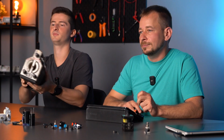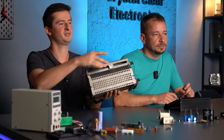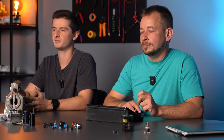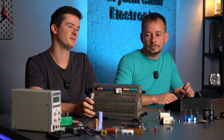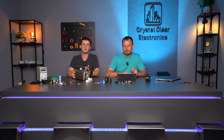It is a power resistance I bring up as an exotic example. You can guess from the multiple outlets and the slider that it is a high power potentiometer. I use it most often to warm up tests on power supplies for my new circuits. The maximum value I can set it to is 5 ohms, so for example I can test a 5 volt supply initially at 1 amp, then by moving the slider I can reduce the resistance, increase the load. At this rheostat I am allowed to run a maximum of 6.5 amps, so in most cases it serves my needs very well.